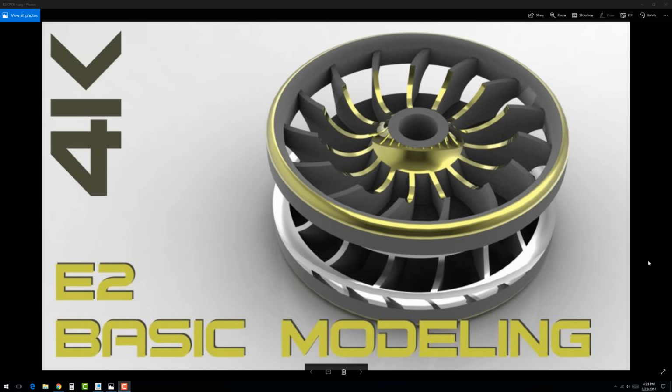Exercise 2. In this exercise, as you can see with Creo 4.0, we're going to go ahead and build what you see up on the screen here. It's not as complex as it might look. It really isn't, it's a very simple little kind of turbine wheel. So we're going to explore revolves, mirroring across center lines for two-dimensional objects, and planes when using 3D features, as well as revolve features. So let's take a look at this.